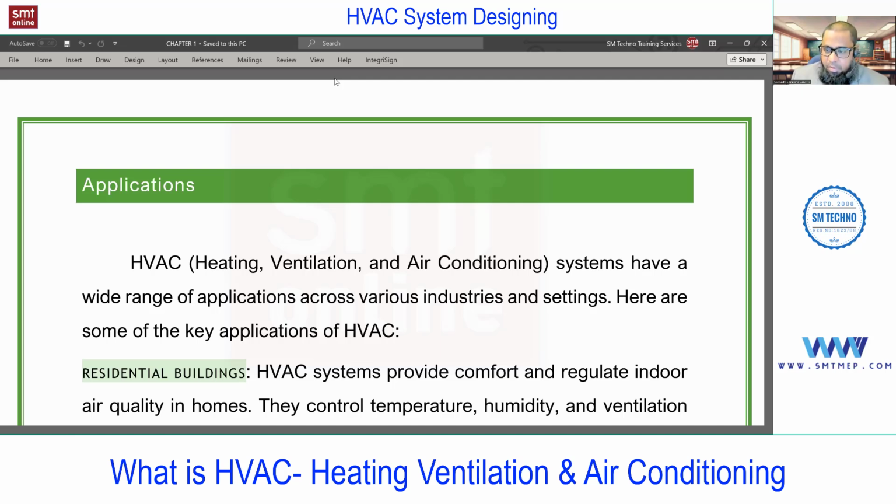As well as exhaust from the inside to outside, right? You see, when you provide the fresh air from outside, what will happen? The pressure in the room increases, no? So definitely exhaust is required. But in most of the cases, we don't require a separate exhaust system. Exhaust can be done, that we can call common exhaust.